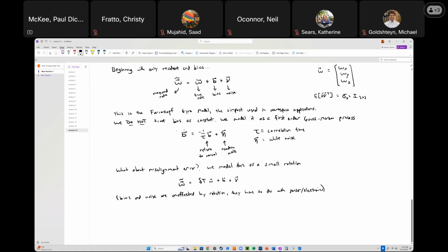All right, now this delta T, that is our attitude transformation matrix. It's going to be a small angle, right? If the matrix delta T corresponds to a small angle vector, we'll call that delta phi. So we're back to angle vectors from lecture whenever that was.